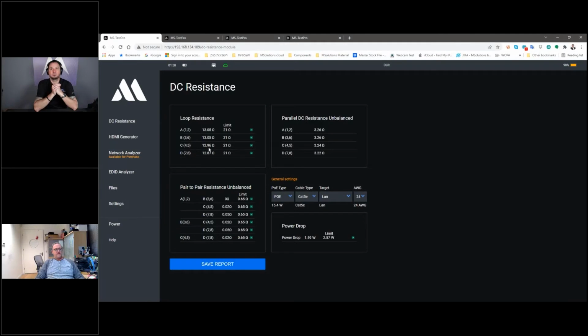You need to understand, when you route the infrastructure, you're bending the cable from time to time. Those bends are increasing the resistance. So we provided a limit for the resistance. If I go with the same cable and change it to HDBaseT, you will see that this limit immediately drops. It drops immediately because we have an asymmetric link, we don't have retransmission, and we did a lot of calculation and measurements to see that it will fit.